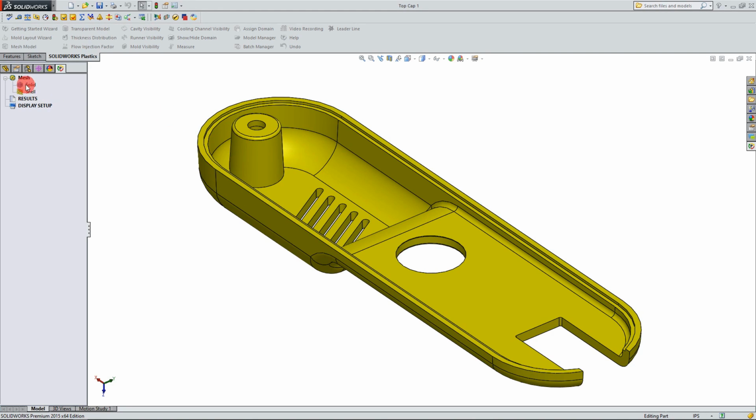So if we choose solid up here under the mesh tab, it breaks the part into 3D blocks. Now if we click shell and use shell instead, it's going to break only the surfaces of the part into 2D shapes. Now this is less accurate because your part is essentially empty. Why would we use shell over solid, you may ask? Because it taxes your computer system a lot less. You would only be using the outer surfaces for your simulation and not the entire part. And so the less computing power that we need, the faster the processing time is going to be, and the less chance that the whole computer system will crash and all those sorts of things. So I'm going to come over here, and under the Mesh tab, I'm going to select Solid.